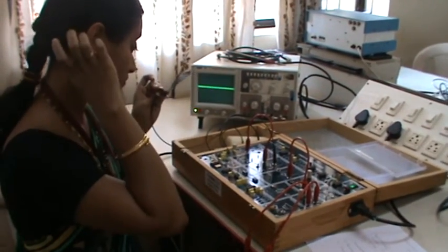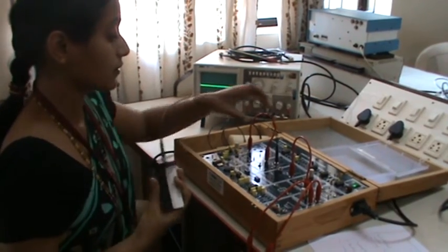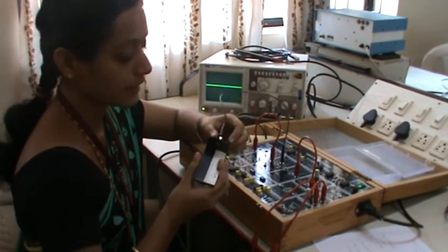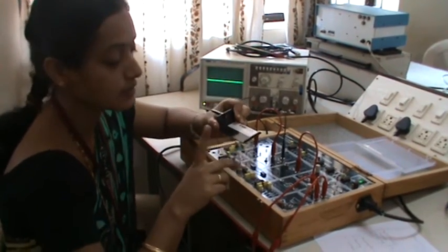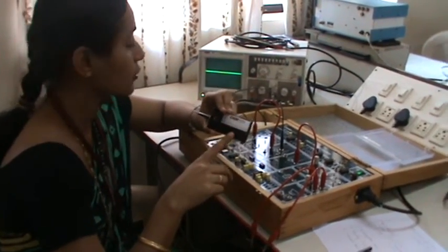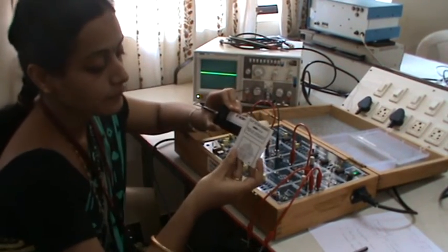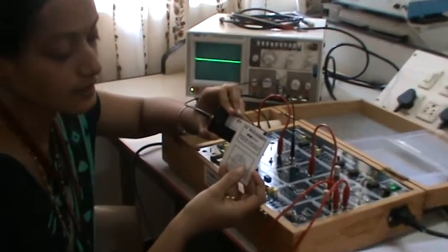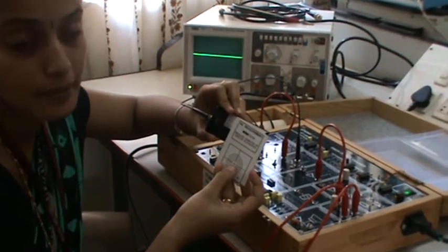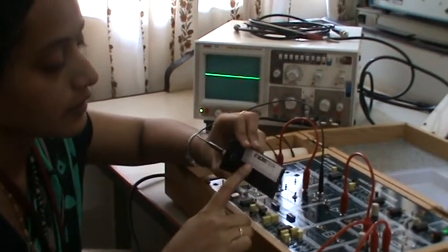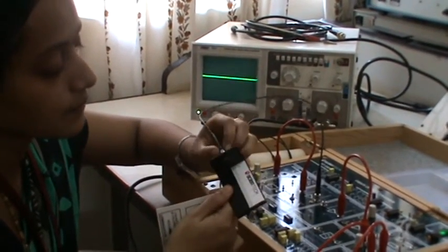So the setup is: you take a 1 meter cable or 0.5 meter cable, whatever it is, and connect it to a measurement jig. This is a device wherein you measure the numerical aperture. It has a wide screen with different concentric circles of 10, 15, 20 and 25 mm. Here this is a length scale.